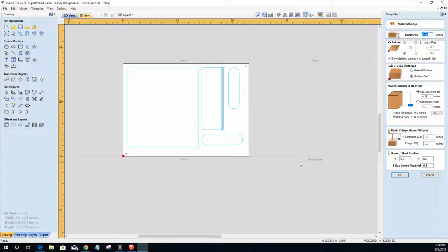Because if I didn't, then when I go to run the toolpath, it would raise up and try to drill the holes in the air 3/4 inch above the wasteboard. So I've got to touch off my tool sensor to the wasteboard, and let it know that is 0.75 inches. If you are using your tool sensor, don't forget to add an extra 0.010 of an inch, so it'd be 0.76 is where you would be. I need you to try to grasp that in your mind.